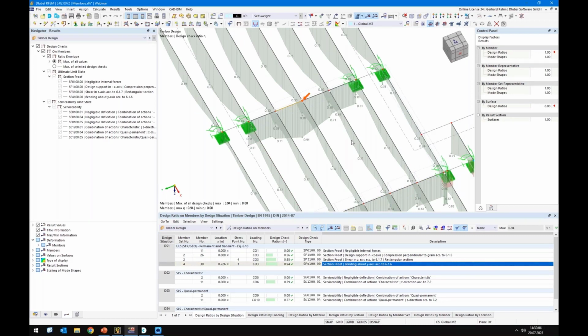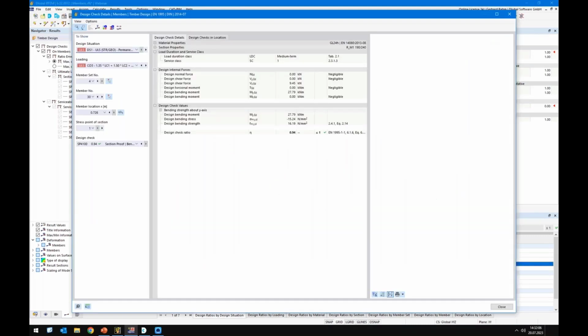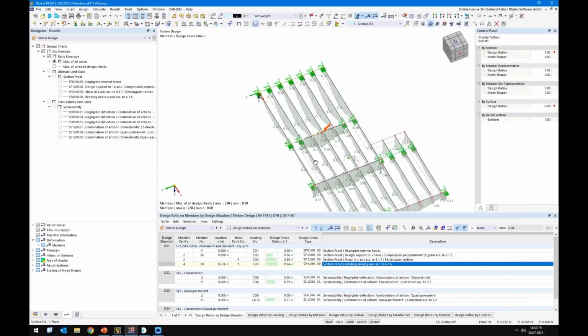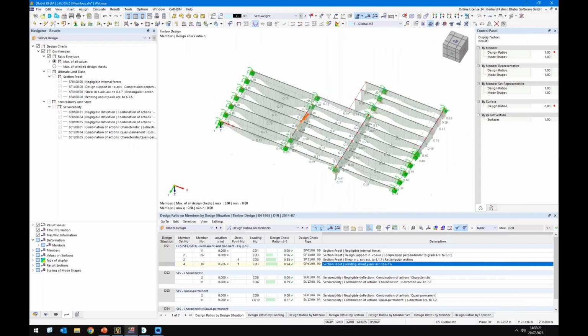Let's have a look inside. Okay, and we will see here, this is the KH factor, and 1.1 by 24 equals 26.3. So actually we have proved the floor, so it's okay according to ULS and deformation.